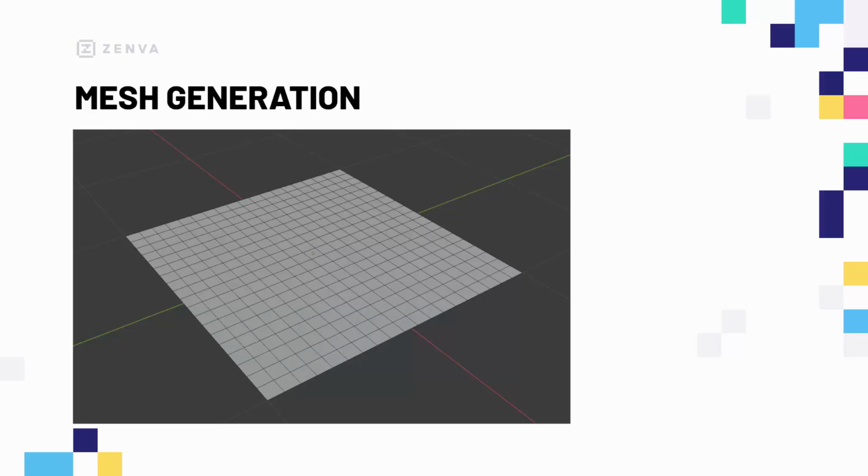And then each of these vertices, all these different points, are going to be the things that we are going to modify. Now, you may notice that if we are having each vertex 1 meter apart, then when it comes down to having very jagged terrain, it's not going to look that good, okay? It's going to be pretty blocky. So what we can then do is increase the mesh resolution by adding in even more subdivisions. And this is where that mesh resolution variable comes into play, that property.